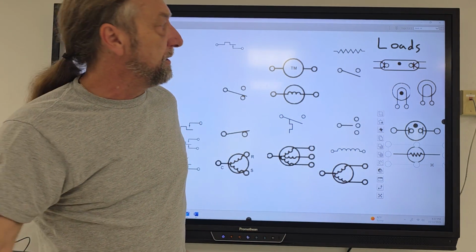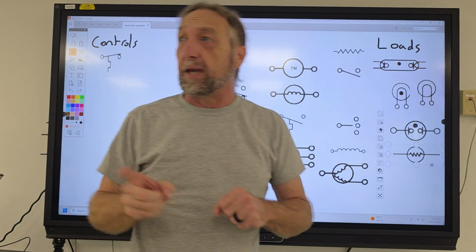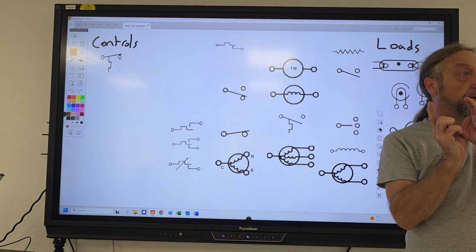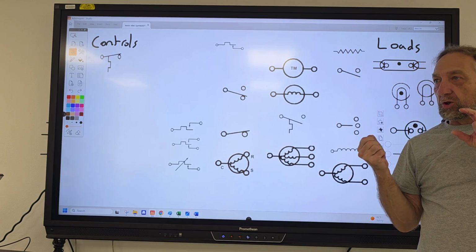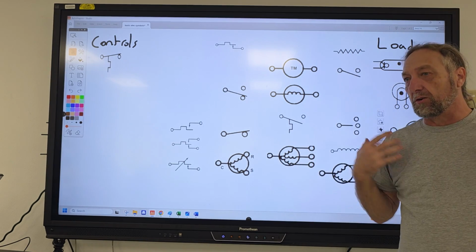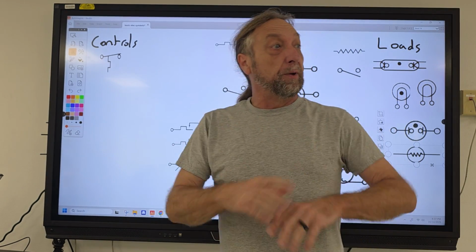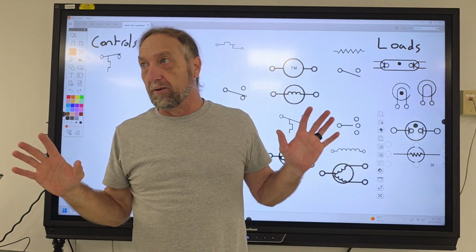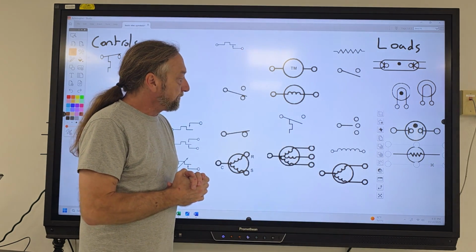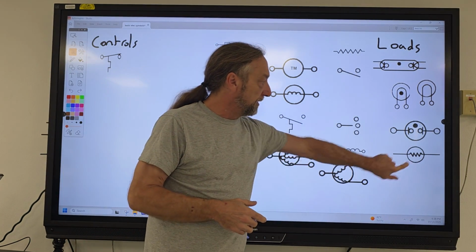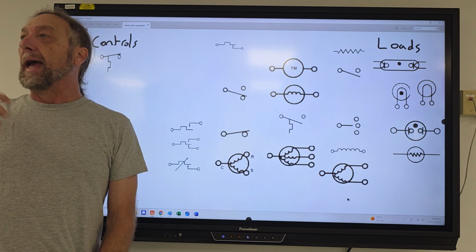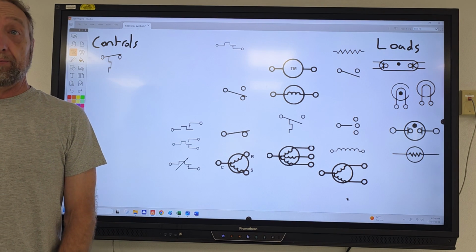You don't normally find thermistors on machines with mechanical timers. Now, they did have some where they would have a small little board, like on a washing machine, and they sense the temperature of the water, and that little board just controlled the water valves. But as machines start evolving, all of them eventually are going to be eliminating timers altogether. Eventually, you'll never see a timer. Everything's going electronic. Okay? So that thermistor is a sensor, or it's a load because it has a resistance value, and its value can change, and it has a job to do.